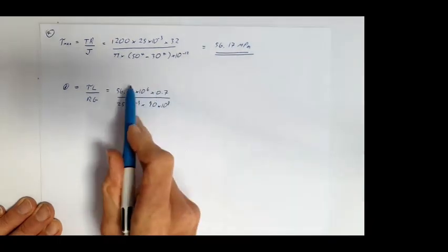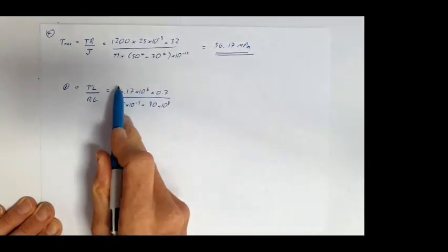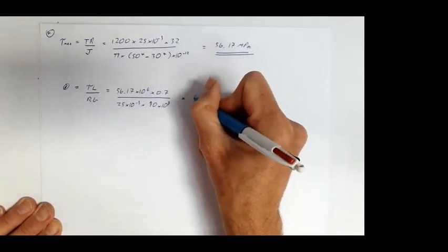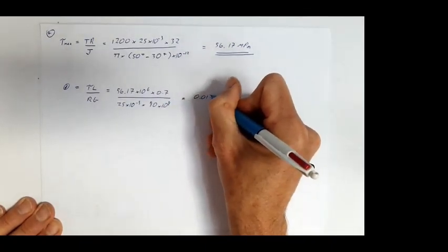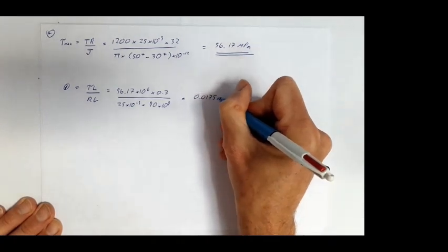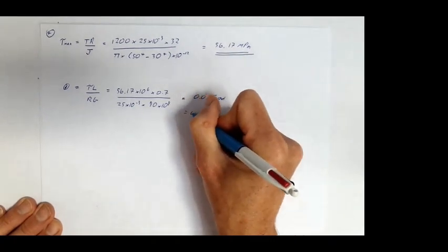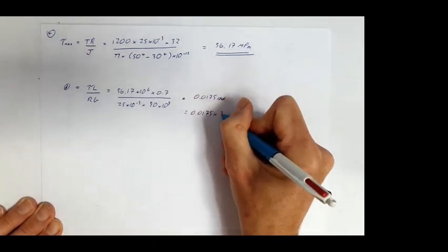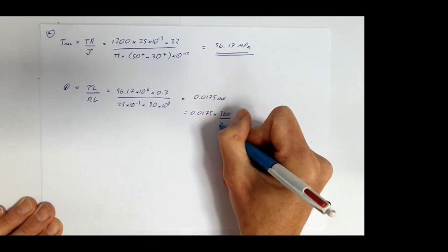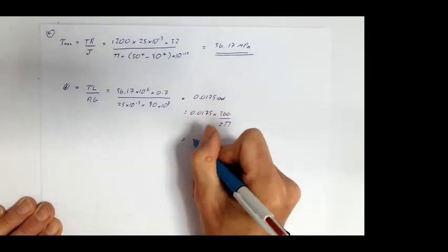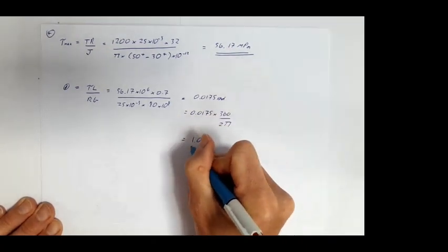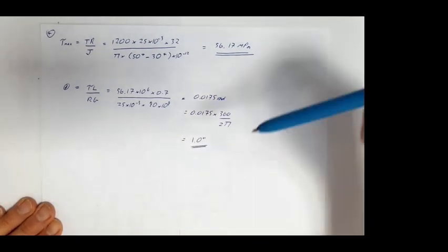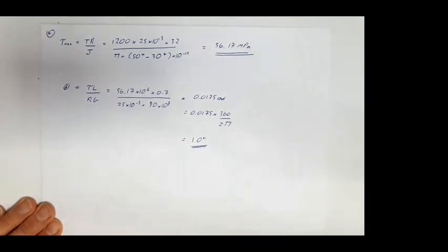So that sum is exactly the same as before. The only thing that's changed is my shear stress has increased. And so because of that, my angle has increased to 0.0175 radians, which is 0.0175 times 360 divided by 2π. That is actually 1 degree. Before the shaft twisted by 0.87 degrees, it's now twisting by 1 degree.